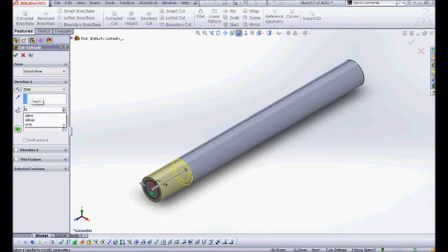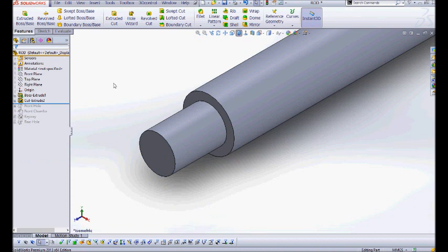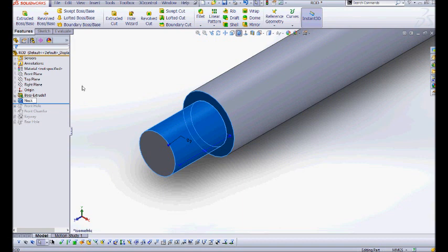So it's another fast way to do it. I'm going to show you that again. Okay, first I hit the plus here to expand it. I select origin right here. Then I hold down my control key and I select the center point. So now I've got the 2 points selected, the center point of the hole and the origin point, and then I can say coincident, and that will add the coincident relationship, and that origin pops right into the center.